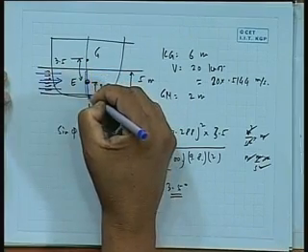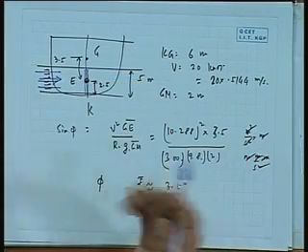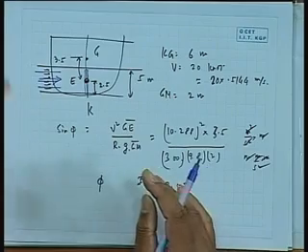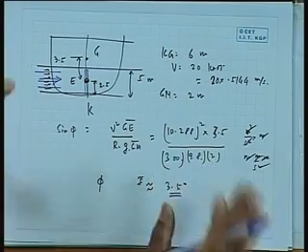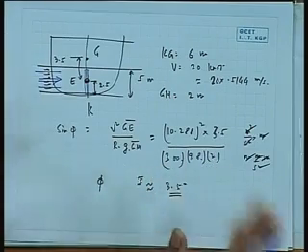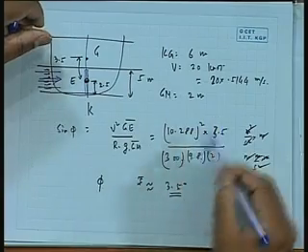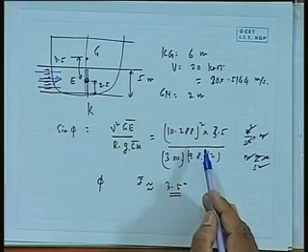The rudder is always more or less on the draft. Where will be the center of pressure? It will always be, if not the center, within plus minus 10%. So you don't go too much wrong. If you don't like 2.5 meter, you make it 2.25 meter. You will get probably a little more, maybe 3.8 degree. So it will be of that order. You are making an engineering judgment. When nothing is there, you have to use your kind of judgment on that. That's what I am trying to say.